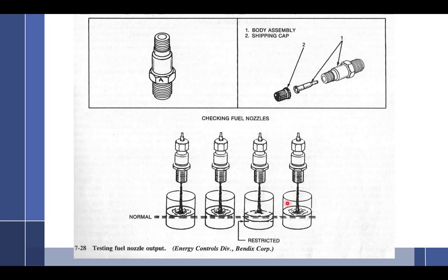Turn on the boost pump, full rich, and let it run. It's just that simple. You can add some throttle, but it wouldn't do much, because mixture is the only thing that you really need turned on. It wouldn't do much because your engine-driven fuel pump is not running. You have no air metering force.